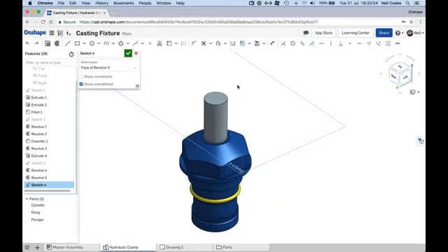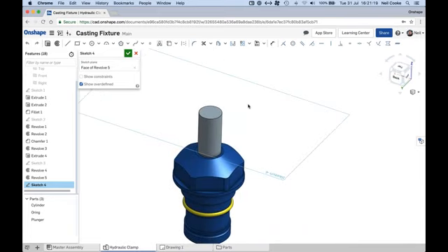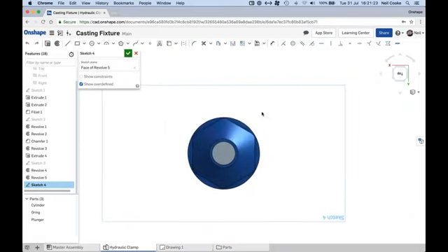Now, very similar to both systems, you select a face or a plane to actually sketch on. Creo, although it does it a lot in the background these days, does force you to select a horizontal reference so it knows which way is up. Onshape doesn't really do that. In fact, it basically assumes a direction. So if you press N on the keyboard, which gives you a view normal, you can see I'm looking at this thing upside down.